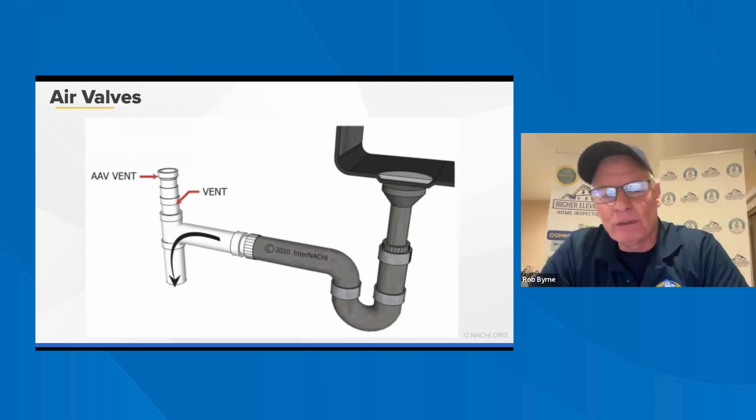Protection in snow regions, vent pipes should extend above the expected snow level to prevent blockage, and open tops should be protected with approved covers and screens. Also freeze protection. Location rule, vent terminals must be at least 4 feet below or 3 feet above any operable window or air intake. And sidewall vents must terminate at least 10 feet from the property line with screens to keep out pests. That's a big thing, to have the screens if you want to keep pests out.